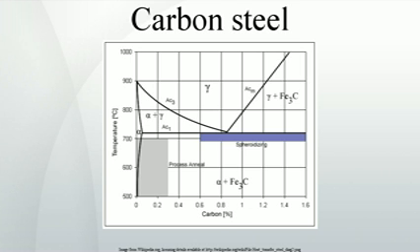Full annealing. Carbon steel is heated to approximately 40 degC above AC3 or AC1 for 1 hour. This ensures all the ferrite transforms into austenite, although cementite might still exist if the carbon content is greater than the eutectoid. The steel must then be cooled slowly, in the realm of 20 degC, 68 degF, per hour. Usually it is just furnace-cooled, where the furnace is turned off with the steel still inside.